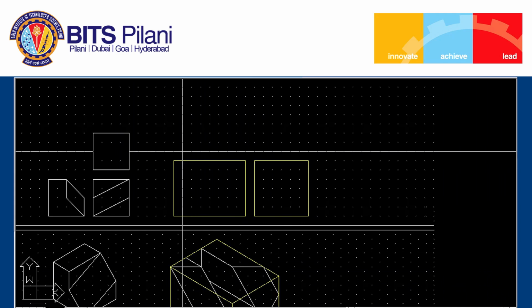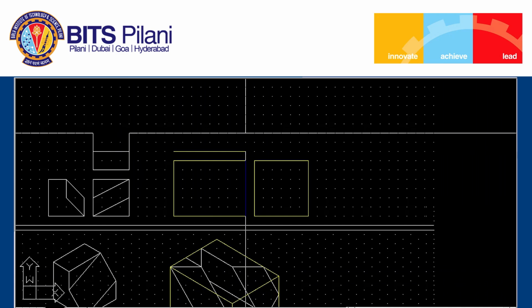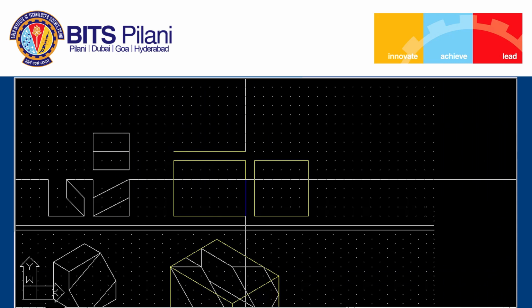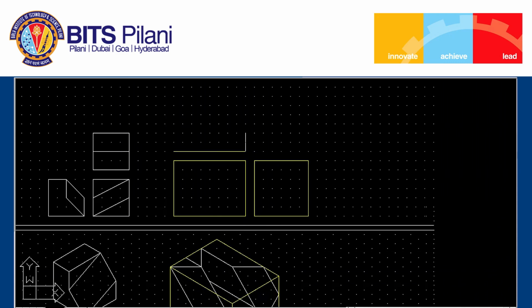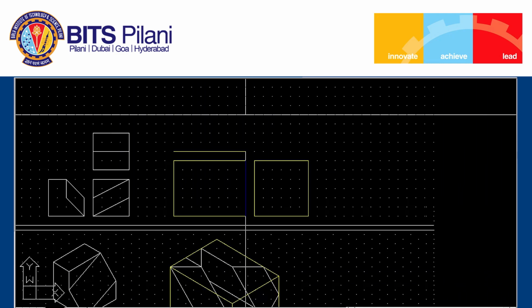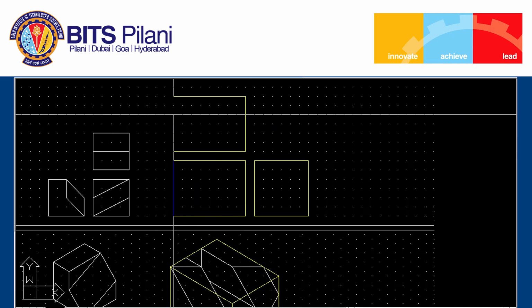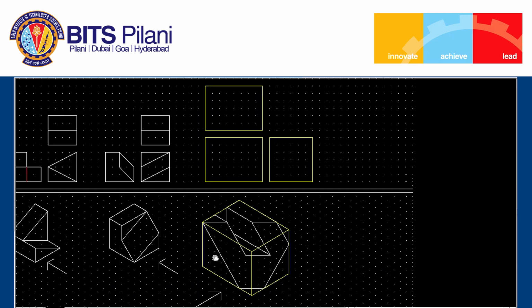Top view exactly above the front view, 8 by 6. In the front view I can see this particular surface which has a height equal to 6 grid spaces and length equal to again 6 grids.